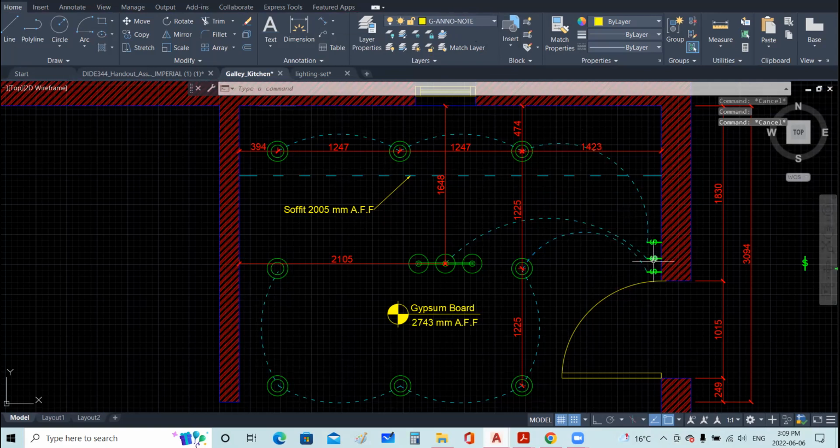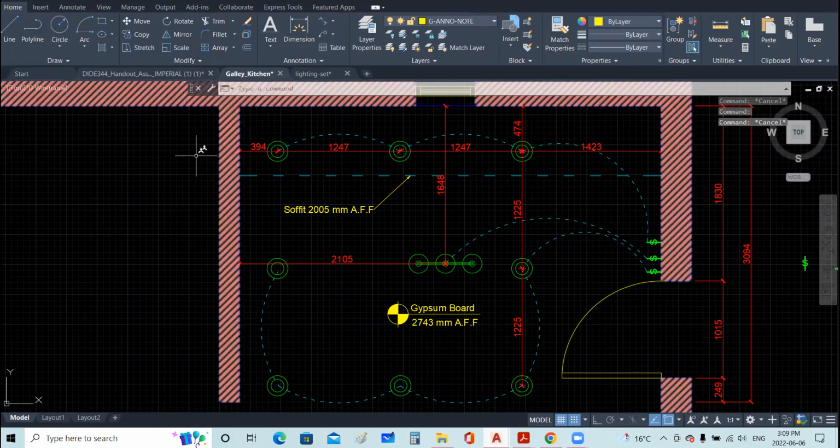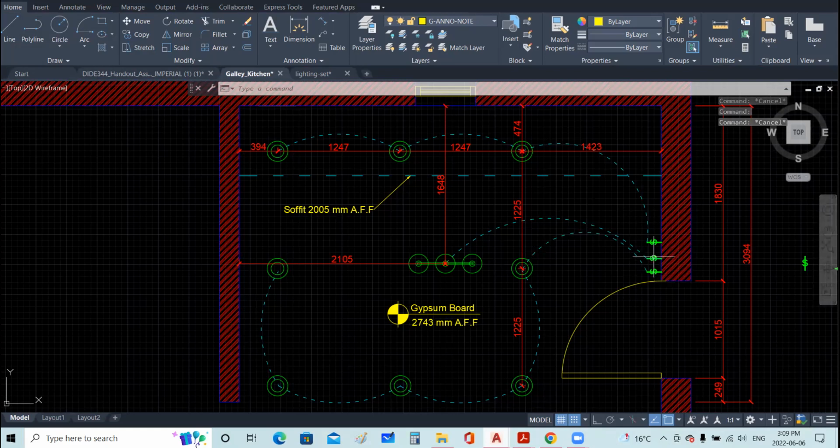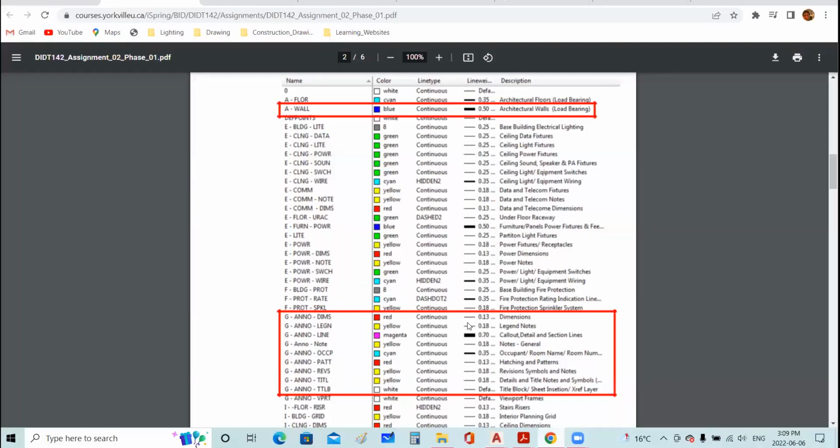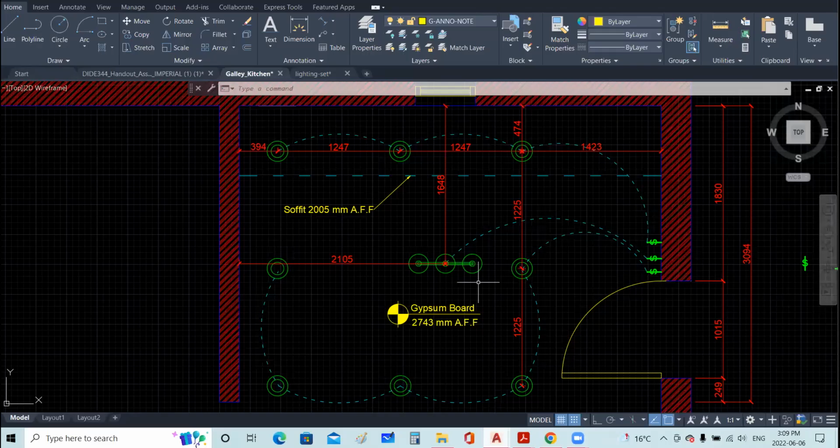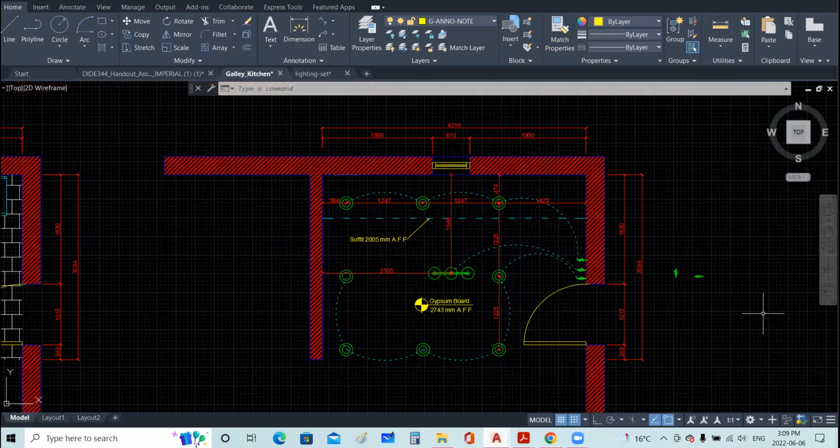And then the switch, and how to create the switch using the polyline, as we said, is fairly easy. The switch belongs to E ceiling switch. If you have a dropped ceiling, this belongs to the I ceiling suspended. We may look at all of the layers that we have here, especially those ones with an E, because those are mostly the ones where I got the designation for the layers from. So that's how a ceiling plan or a lighting plan should look like.